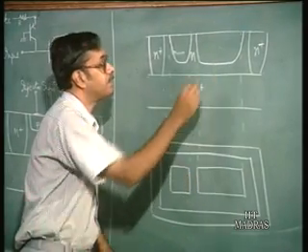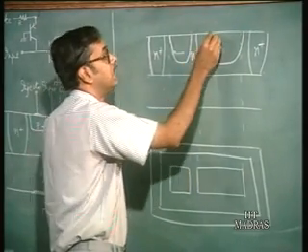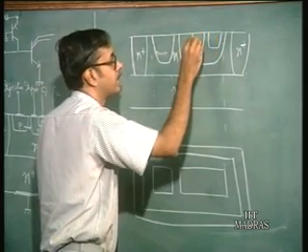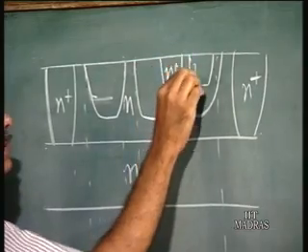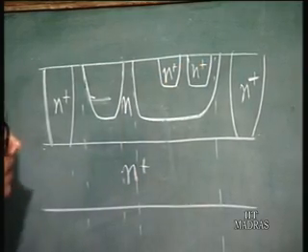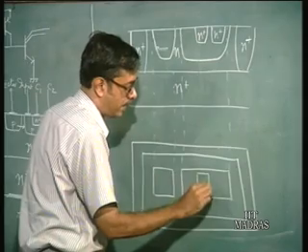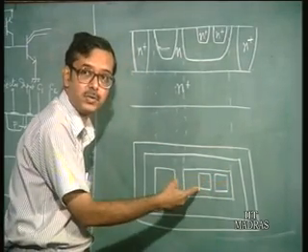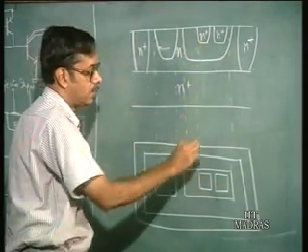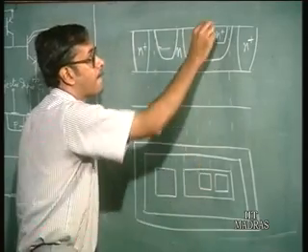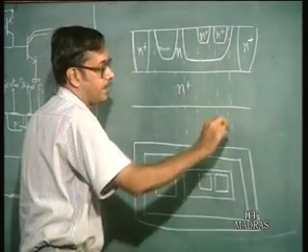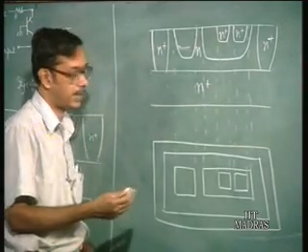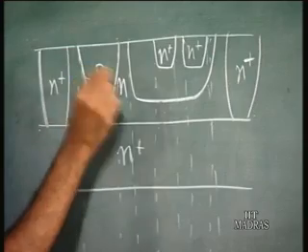So this is the P region, and then the next step is you diffuse the collectors in the P regions. So these are N plus. This is the mask through which you diffuse the N. This corresponds to these regions. And then finally, these are P.